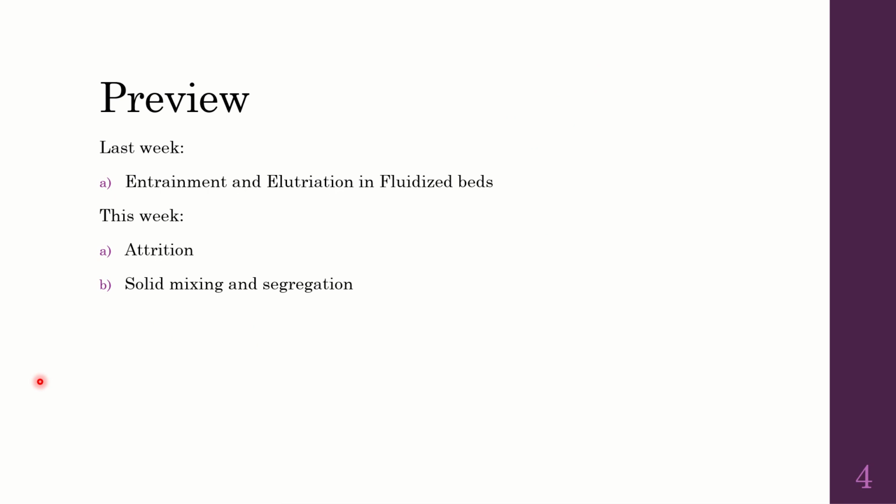And finally we are coming to mixing and segregation. It is very important to know the mixing and segregation behavior of the solids inside the bed. The vertical movement of porous particles carries adsorbed reaction components up and down the bed, so this lowers the conversion. There is sometimes a need for mixing, and sometimes a need for segregation. So depending on it, we should design the bed wisely.